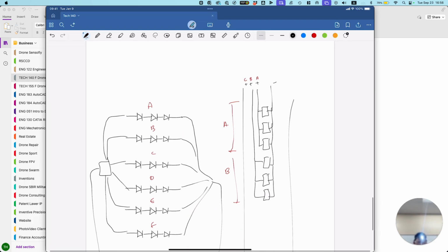So what you have to do if you want to actually fix this, you have to take that knife, scrape away at the board, expose each of the lines to each of the 6 segments plus the ground, and then solder. So that means we're going to have 7 wires you would need to solder, which is going to be really difficult because it's a challenge. You should try it. Actually, not 7.